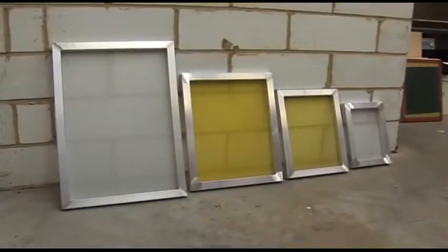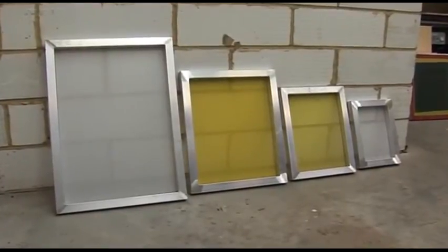The most popular textile mesh counts for garment printing with either water-based or plastisol ink are between 32T and 65T mesh, and a mesh of 77T and upwards would be advised for paper and card printing with a water-based ink. We have chosen a yellow 43T mesh today, although white would be fine also. We have picked a 20 by 24 inch screen, as our logo fits nicely inside with 2 to 3 inches either side, which is a nice amount of room for our squeegee.